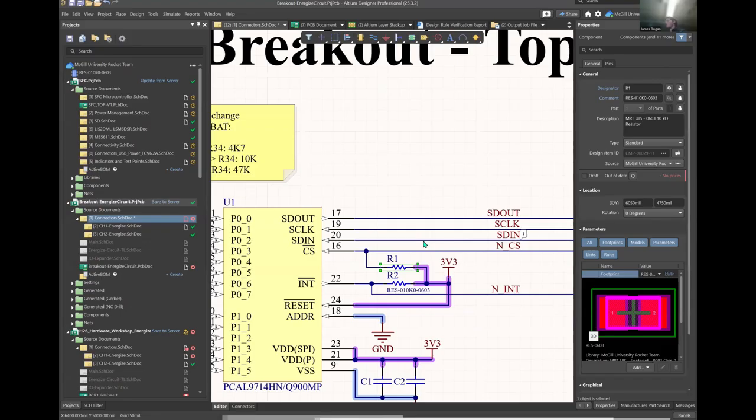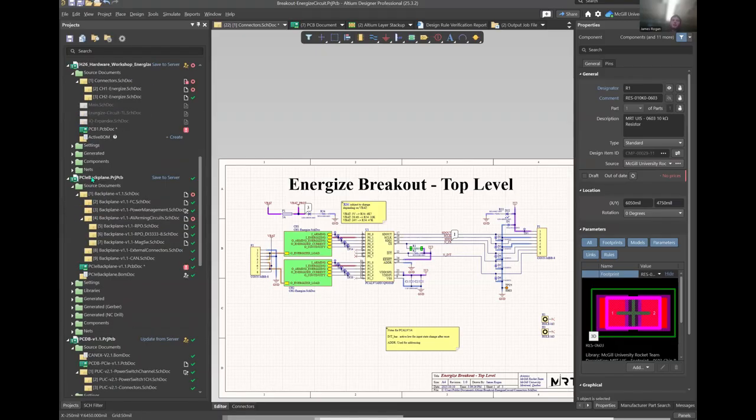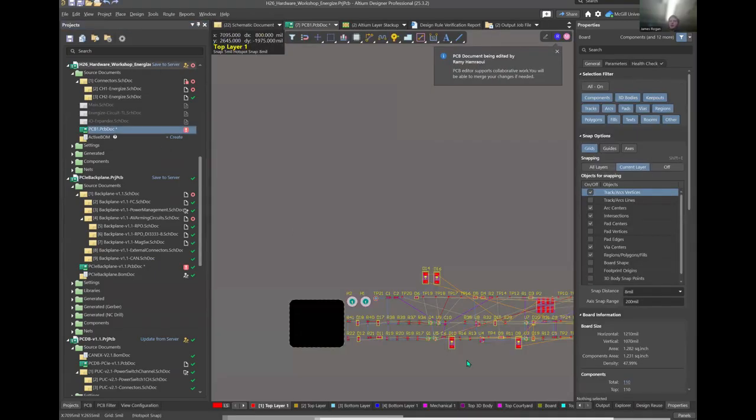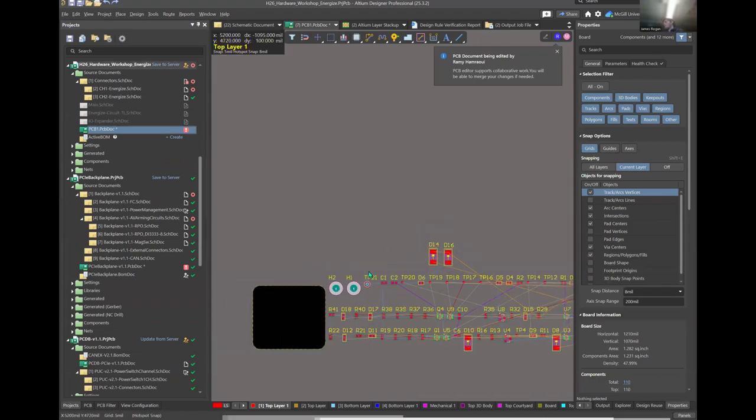And so once you've drawn all of your schematics, I'll go through the process of how you start to think about a design, how you select your components, how you draw your schematics, how you simulate them. And then once you've done all of that, you can move it onto a layout. When you initially push these files to a layout, you'll see something like this, where they're all dumped onto the side of your PCB, which is this little black board here.